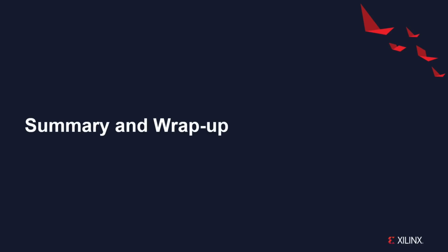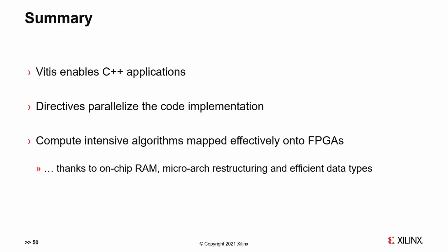Okay, this is now time to wrap up. So we just discussed the Vitis flow and how C++ kernels can optimize untimed portable C++ code to accelerate algorithms via three main pillars of acceleration with the pipeline, SIMD, and DATAFLOW directives. We then illustrated some of the concepts with the traveling salesman problem example, in which we found a very effective mechanism to generate permutations while implementing a multi-port RAM structure on chip to read the distances and calculate the cost at blazing speeds and provide orders of magnitude acceleration compared to CPUs, while also running faster than GPUs.